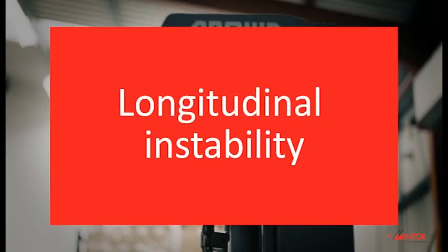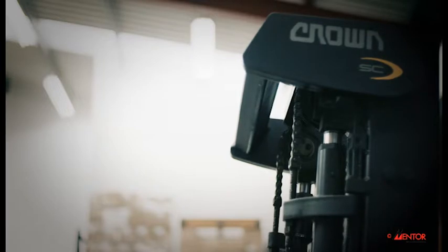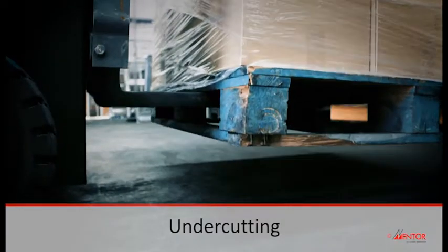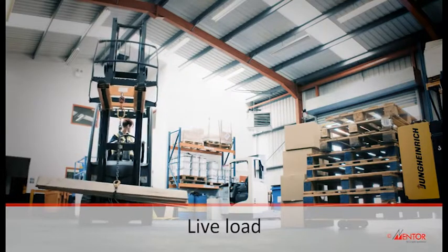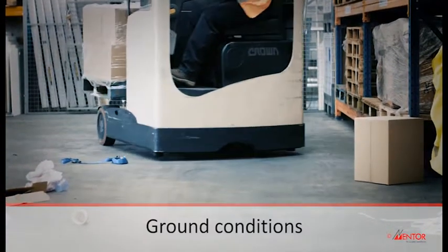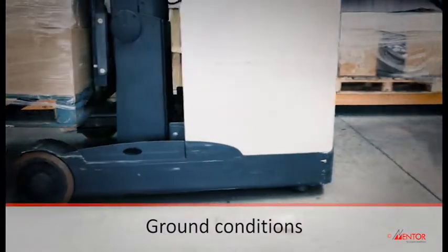Forklift instability can be caused by a number of factors. The main causes of longitudinal, or front-to-back, instability are harsh braking and acceleration, undercutting, not heeling the load, live load, a swinging load that can move the centre of gravity, causing instability, and ground conditions, for example potholes or debris. If a truck needs to be driven over rail tracks or a drainage gully, always drive over diagonally and slowly.